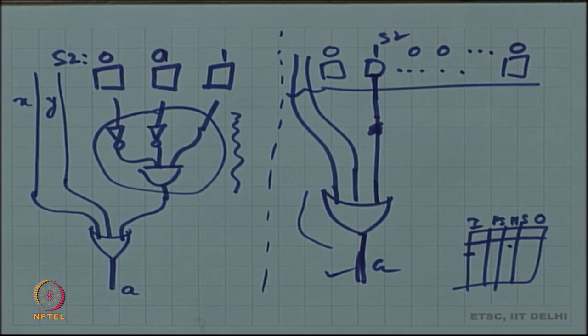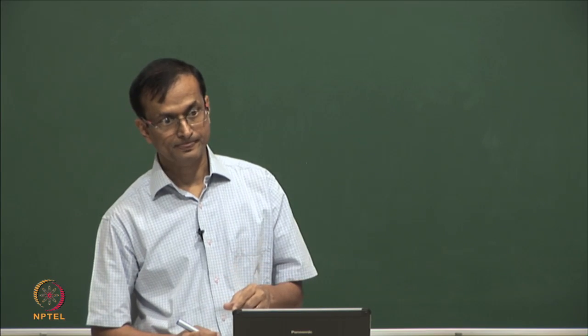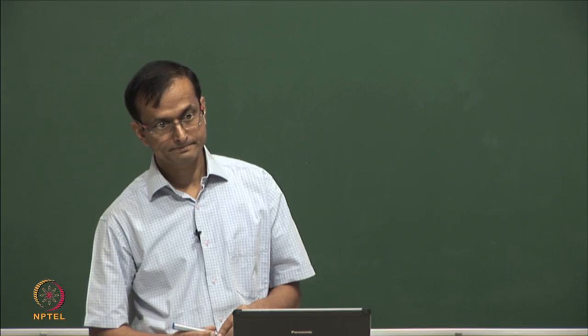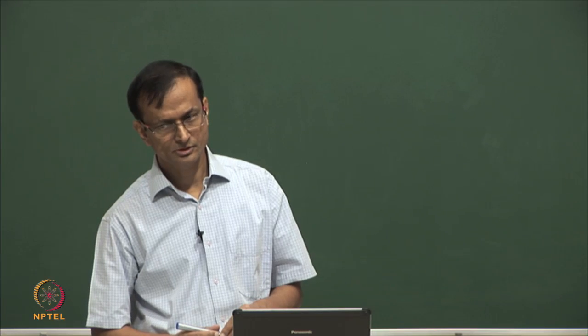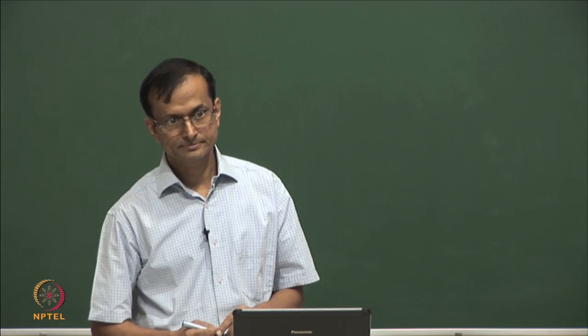Fine. What I'm talking about is like he was saying that when we are calculating the next state, we need to send all 7 signals. 7 D inputs need to be given to the 7 flip flops, right. They would correspond to all those transitions where that particular state is the next state. Okay. So, but the rest of the flip flops can just sit in the previous state. Rest of the flip flops do not change, it is true. So even in the logic realization, we need only 2 lines from every state for calculating the next state. We need to set 1 to 0 and the other state to 1, that's it.